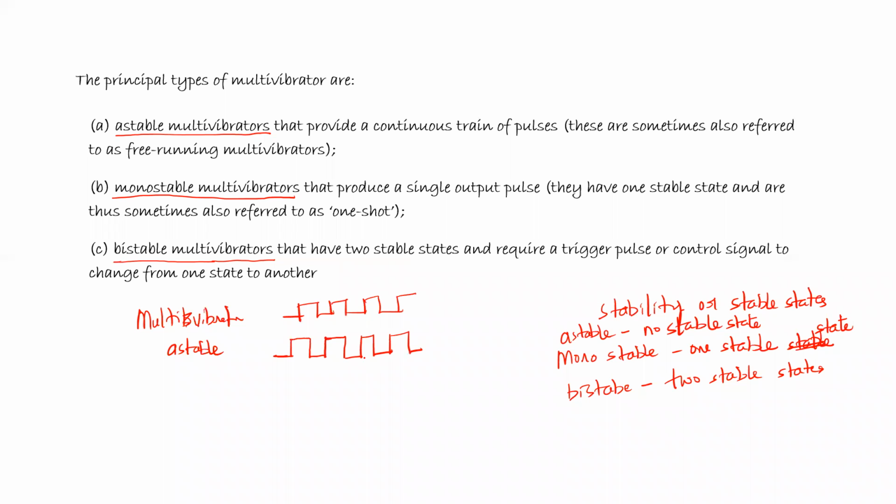Understand that? That's why it is referred to as a free running multivibrator. Astable multivibrators are also called free running. We don't have control over them. Unless we switch off the circuit, unless we cut the supply to the circuit, these free running oscillations will continuously be there. We don't apply even an external trigger to stop the oscillations.